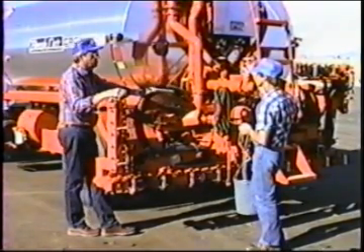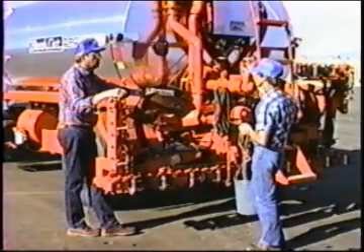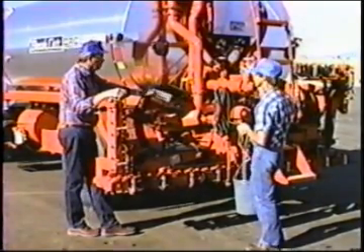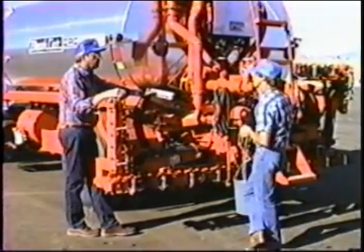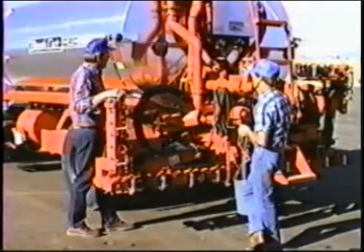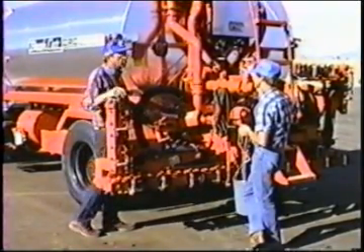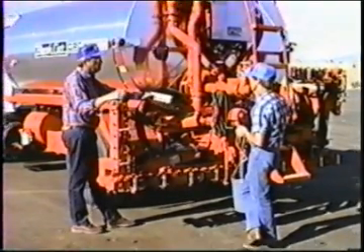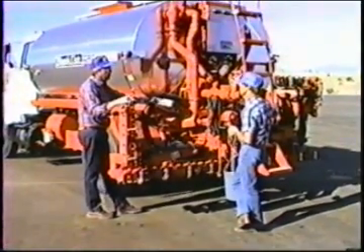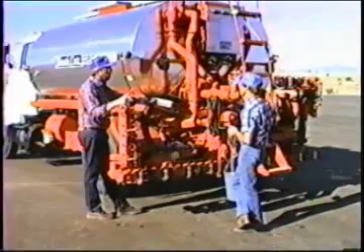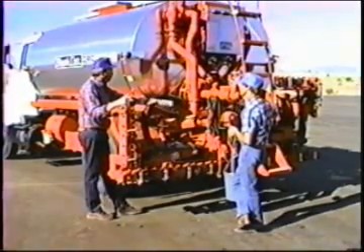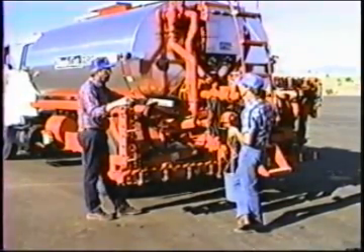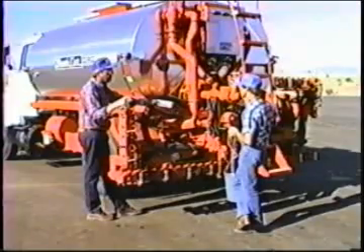So if we speed up, the pump speeds up. If we slow down, the pump slows down. That is the advantage of a hydrostatic asphalt distributor. That is, the hydrostatic transmission gives us this infinitely variable ratio transmission that enables us to do that. Of course, with the computer, we've gone one step further, and now we control the pump with all the numbers rather than just the ground speed number.